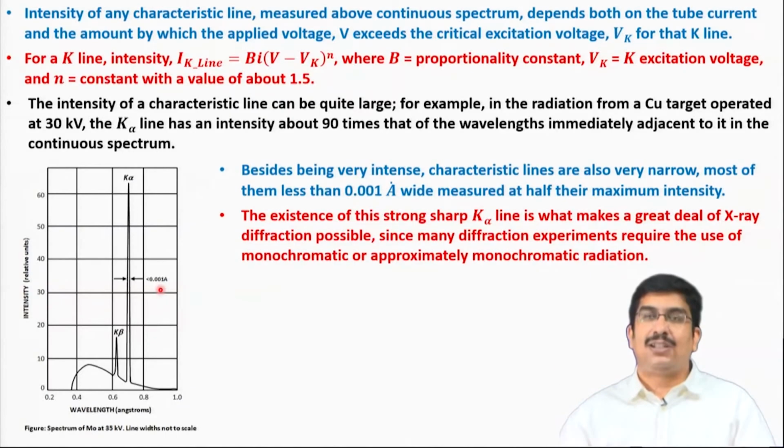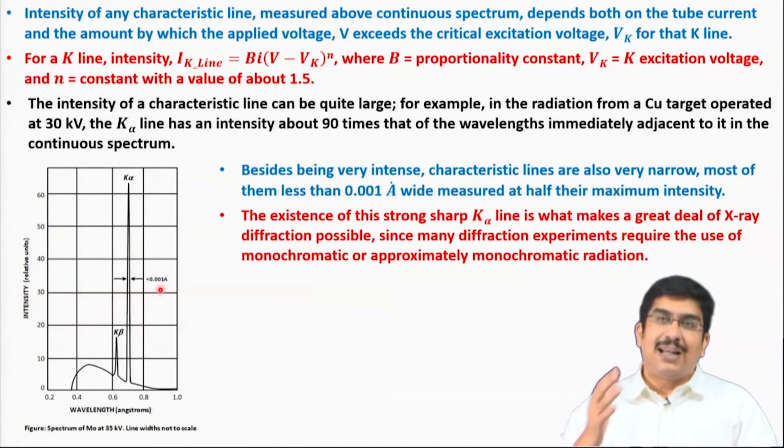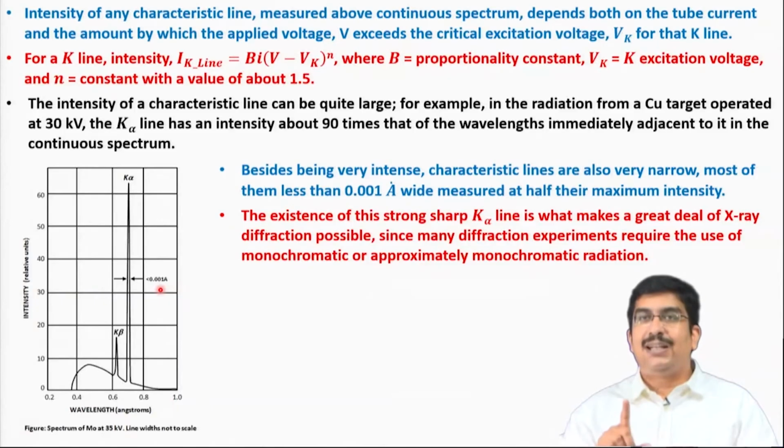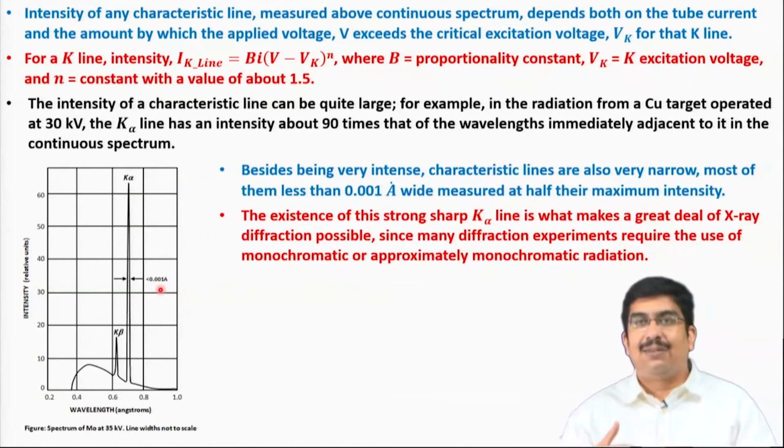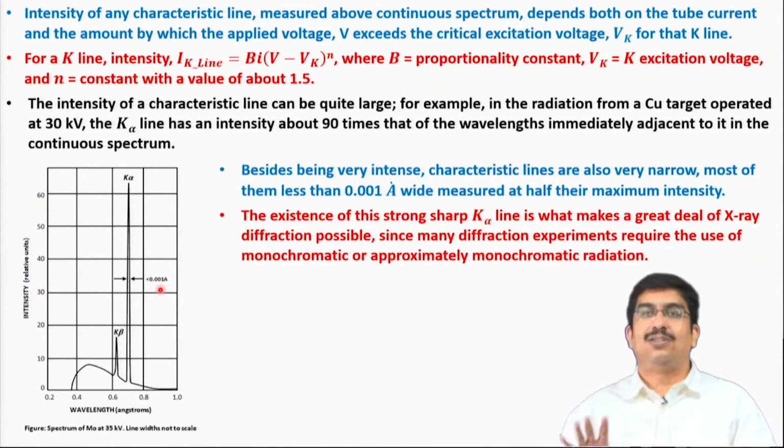So, X-ray microtomography, when we want that kind of imaging, what we need is a continuous X-ray source. Why, we will discuss when we discuss absorption and so on, but there the white radiation is more important, because there we do not want diffraction to happen.